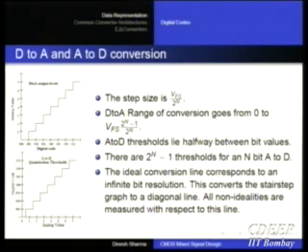Okay? Normally, since you would like to have good resolution and each bit size is quite small, this should not make too much of a difference. But if you have a feedback system in which there is D to A and A to D in the same loop, then you should be aware of this offset.